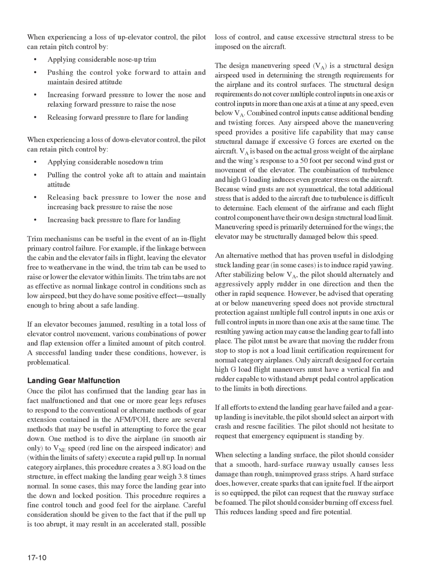Each element of the airframe and each flight control component have their own design structural load limit. Maneuvering speed is primarily determined for the wings. The elevator may be structurally damaged below this speed.